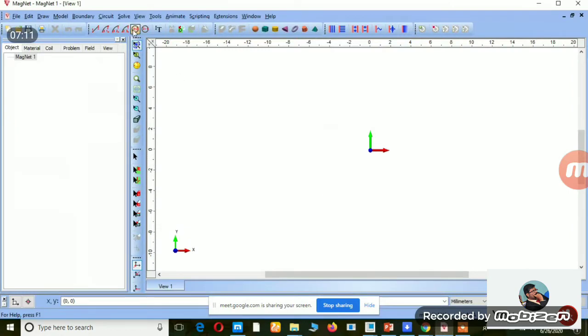So I just select the circle here. If you hover over the circle icon, the circle icon is found at the top, right? There is an add circle option available. In this case, it is having center comma radius. So now I just want to initialize the center. Center means nothing but it is 0. It is the origin point. So I just give 0 comma 0.